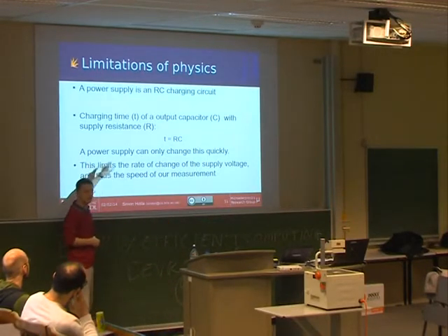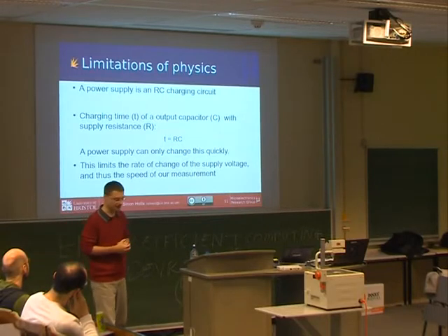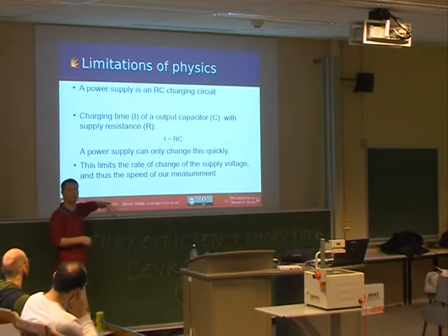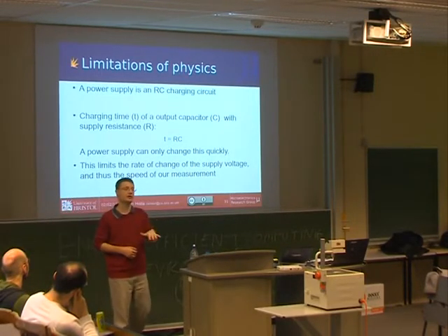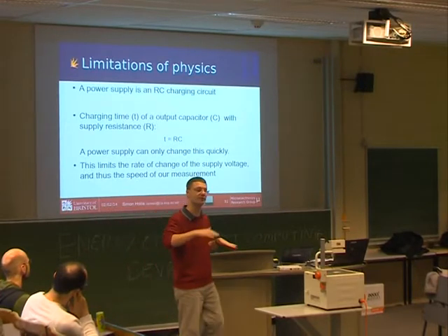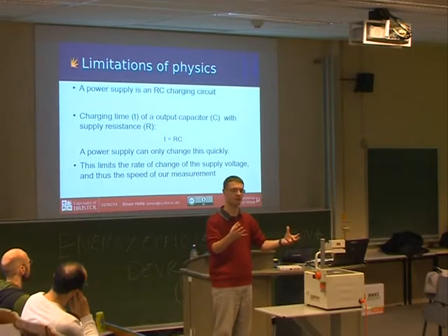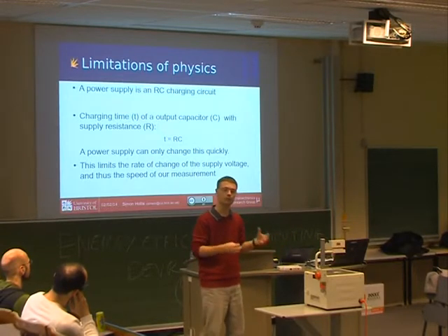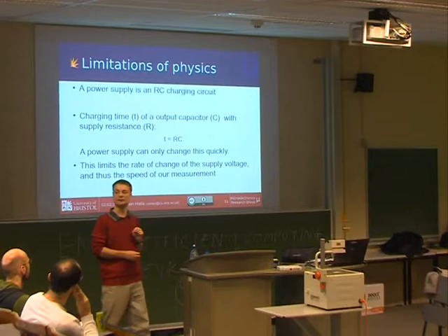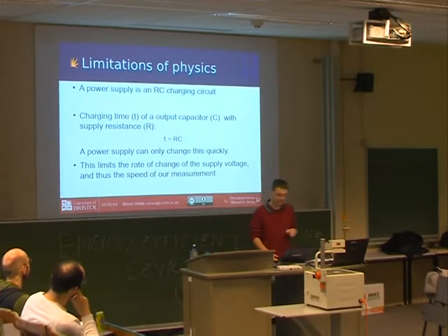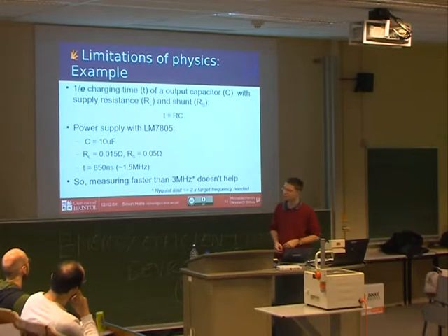And what that means is at the point where you're coming out of power supply, the voltage can only change so quickly. And it changes a maximum at speed. And so that limits the rate at which the power supply voltage will change. You'll see it change there. Regardless of if the microprocessor suddenly connects together power supplies and says, I want infinite current now, you won't see that for some time on your measurement. You will see it eventually, but you won't see it straight away. And that means that you can then push through values.